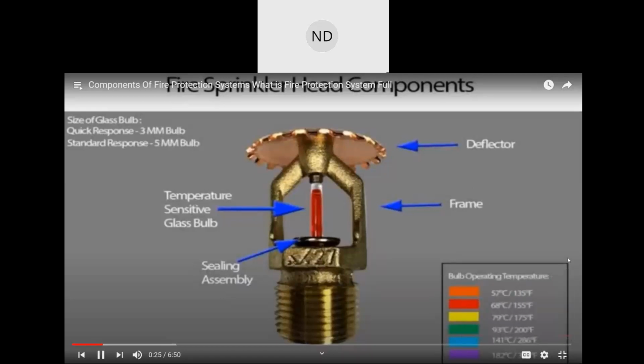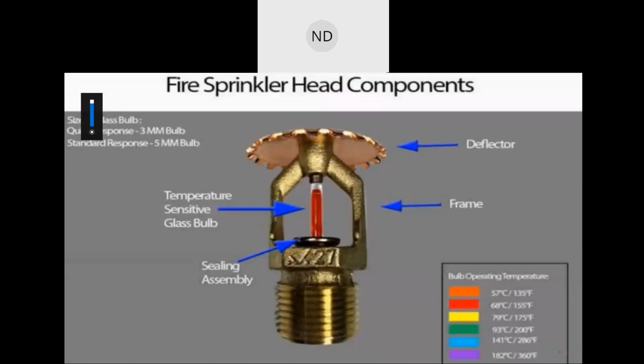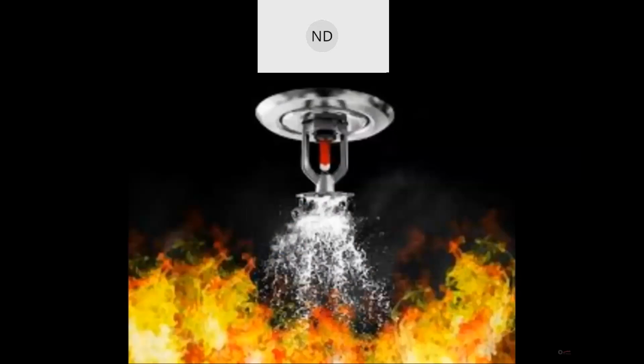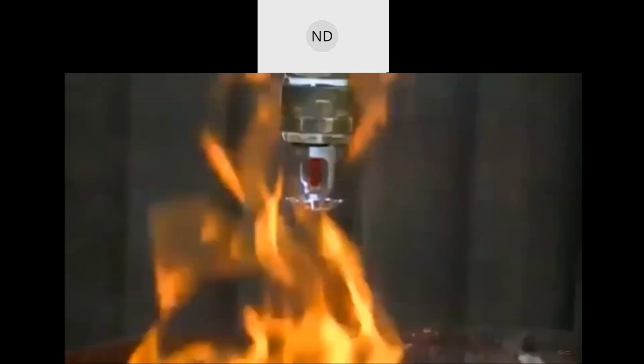A common misconception is that every sprinkler head in a system will go off at once after the first sprinkler has activated. While systems that behave somewhat like this exist, deluge-type systems, it is pretty uncommon and used in special situations like certain types of aircraft hangars. In most cases, the fire sprinklers that activate only do so around and over the fire.